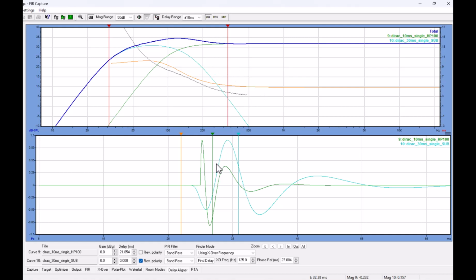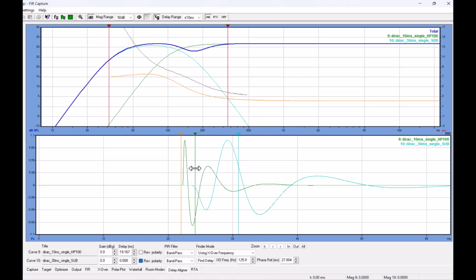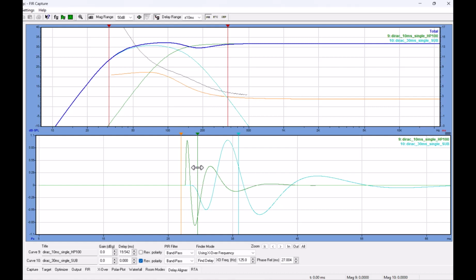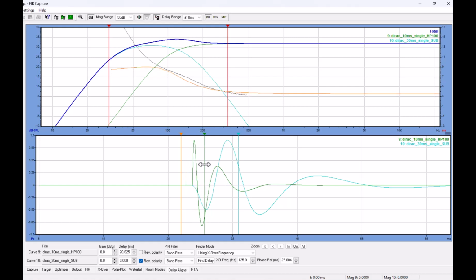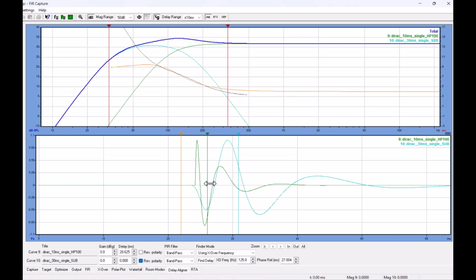and in that way you have the ability to see how the impulse response looks. And here is a trick I learned from a good friend called Paul Baumann. He had been director of Hell Acoustic and JBL before, and that is that if you filter out the impulse response, then you can have a very accurate alignment by taking the second oscillation of the top and then aligning that to the largest swing of the sub, like this.